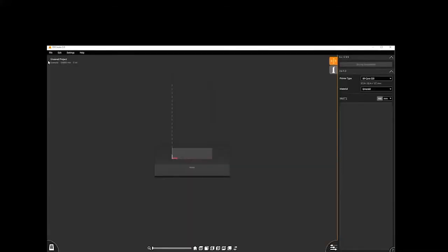One other thing that I want to call out, right now it says Unsaved Project here, right below all of those menu options. It has a material type, so whatever material you have specified will be shown here. It will save your project name up here in the corner when you have saved a project. But two important pieces of information are the build height and the build volume. So for our FastWax users, when they are trying to find out how much build volume their model has, this is where you would come and find that information.